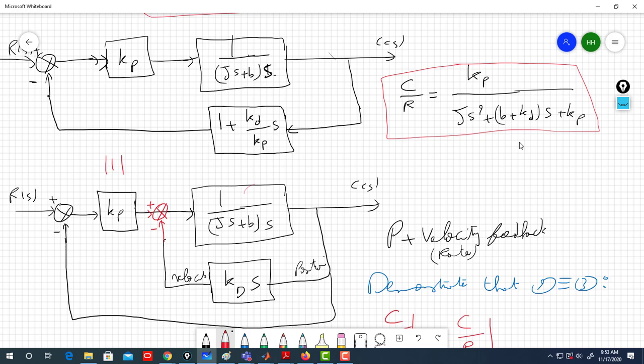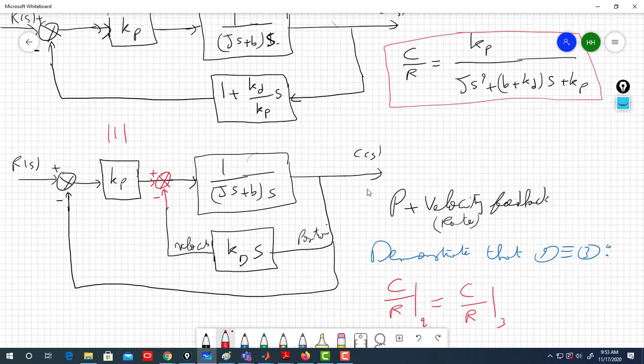It will give you the desired system, because here you have two parameters you can play with, Kp and Kd, to position your poles at the desired location. So you can choose the desired location, but without the negative effect of the zero. If you remember, to reach your desired point you need to go back, then later on go up. So you eliminate this negative effect of zero.